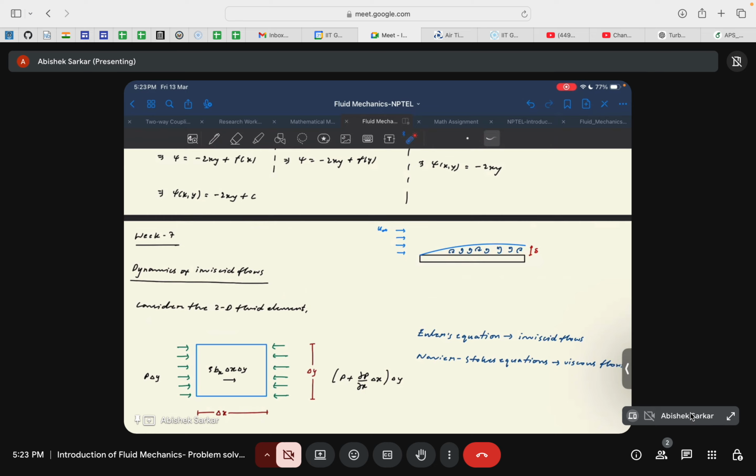Now, what this boundary layer does is that it creates a demarcation, by defining it in a way that we say the boundary layer extends up to a region where the flow velocity is at 99% of your free stream velocity, that is u infinity. Okay, why 99%?